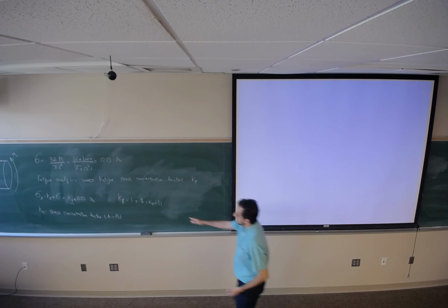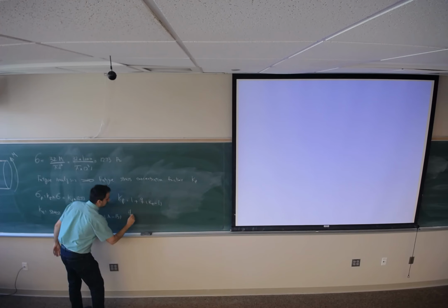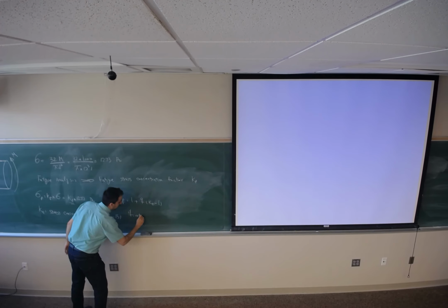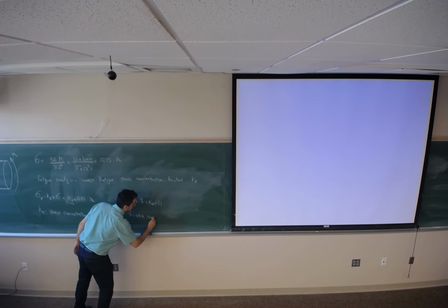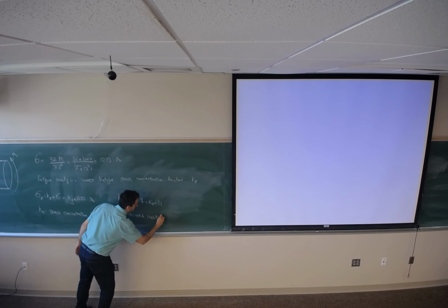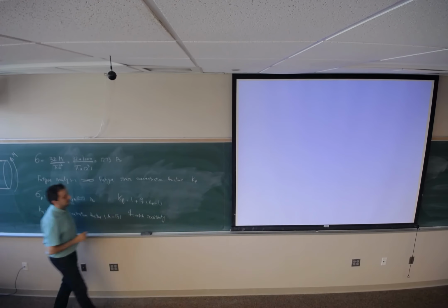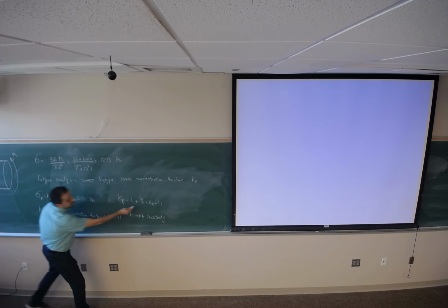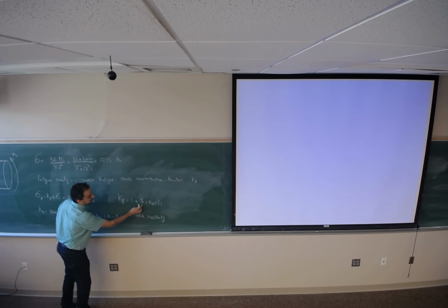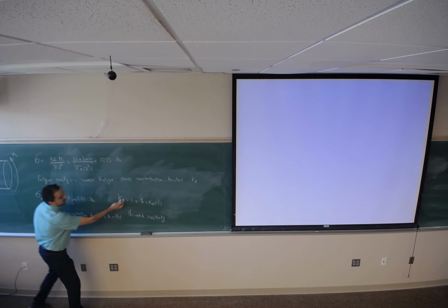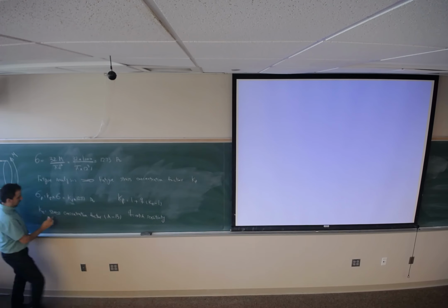What is q? q we call notch sensitivity. q is the notch sensitivity, representing the sensitivity of Kf to the stress concentration factor.